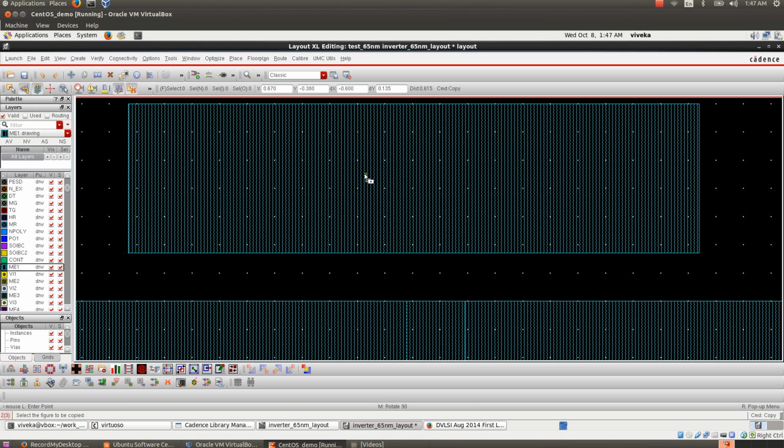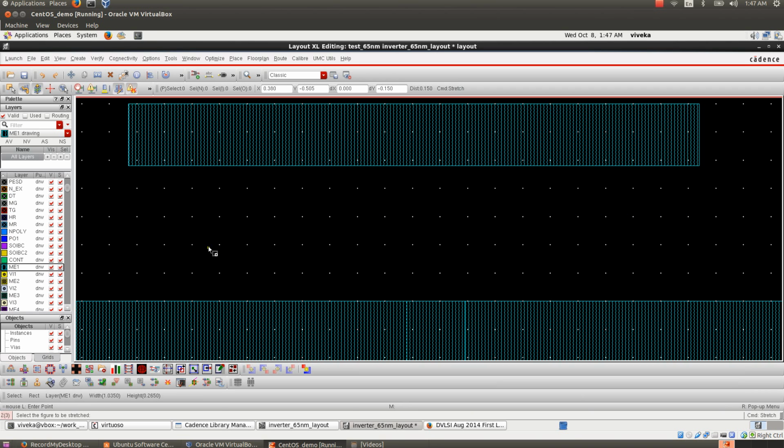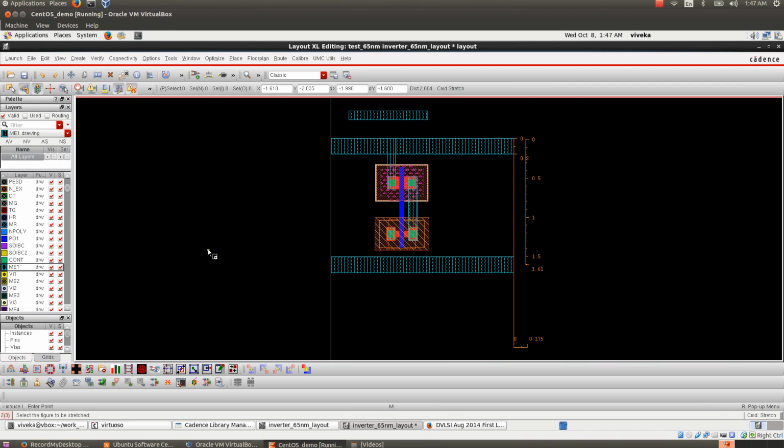If I hit C and move my mouse pointer in between, you see that the entire block highlights. The light yellow border comes across on the entire block. However, if I hit escape now to undo that command, deselect that move command and then hit S, you see only that particular edge highlights. When this happens, I can click there and then scale that. So that can be used to resize rectangular blocks. So let me select that and hit delete so that that thing goes away.